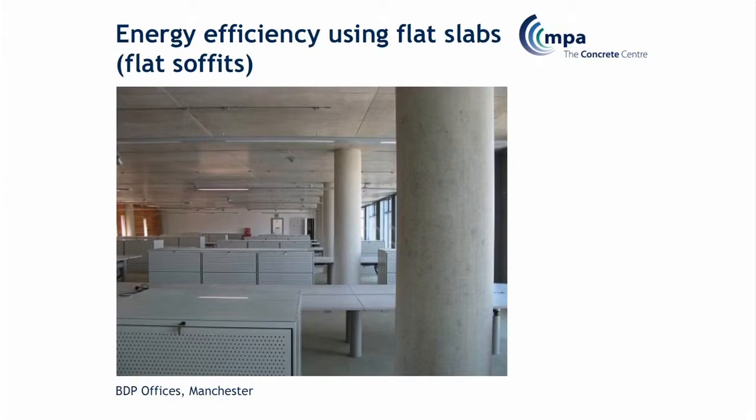In fact, normally what happens is you end up putting an extra story in. But that's useful. That's good resource and land efficiency as well. Post-tension slabs are flat slabs, so they provide flat soffits. And again, that's another way of thinking about it.